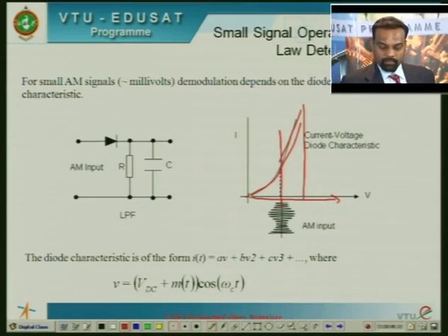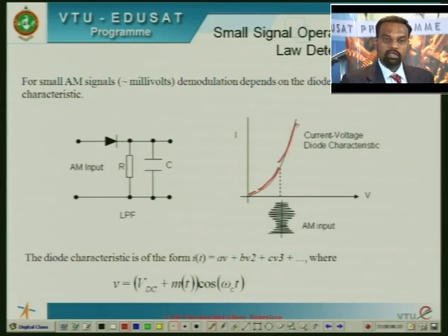And if you look at the variations here, there is a non-linear relationship between voltage and current, because here it may be linear, again it is exponentially varying, again it is going to vary in a different slope. Because of the variations in the slope between the voltage and current, we call a diode a non-linear device.